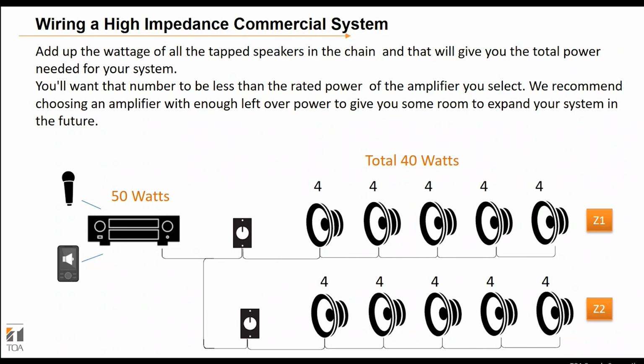So you might have 10 speakers on the line that are all tapped at 4 watts, as you see here in the image. That's going to give you a total of 40 watts. 4 times 10 equals 40. Very, very simple to do that math. So it's one of the reasons why commercial audio is set up this way, is because the math is just so much easier to do when it comes to putting a lot of speakers on a single line.